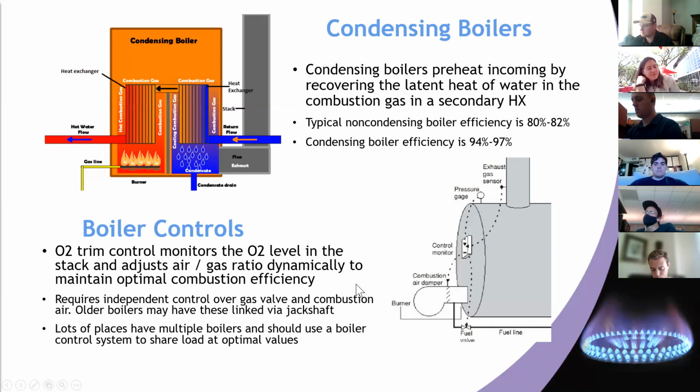A lot of times, we have the ability to log current on a lot of the pieces of equipment we see in a factory. The only place to do electric logging on a boiler is usually on the combustion air fan. And that combustion air fan will tell you how often and how intensely that boiler is burning, because whenever there's combustion going on, that fan will be running and supplying the air, the oxygen that's required for that burn.